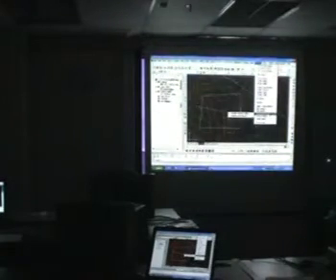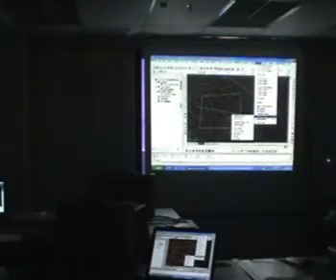The second method is the composite method, which can only be done by the software. It's not possible to do this manually. A lot of people also call this the DTM method. DTM stands for Digital Terrain Model. This takes a direct comparison from your original ground level to your proposed level, and you get the volumes from there directly. The third method is the section method. The section method is another very popular manual method where they basically cut cross sections across both the existing and proposed level. They take the difference, multiply it, and total everything up together, and they get the volumes from that.